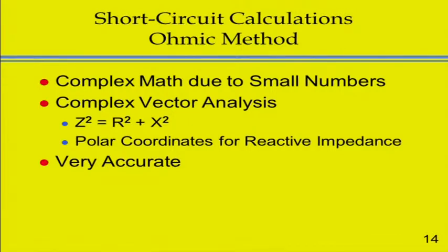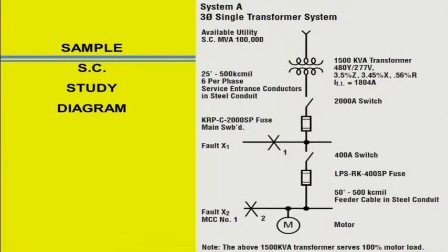And so in order to do a short circuit calculation on a standard industrial system, we'd have a one-line diagram that we'd start with. And this starts out with asking the utility company right here at the source, okay, if we have a dead short in our facility, how much current can you deliver? And that's usually given in terms of megavolt amps, how much power that utility company can deliver. And then you have to know the size and distance of the conductors to the main transformer, the size of the transformer in terms of its kVA rating and the different impedances that it's rated for.